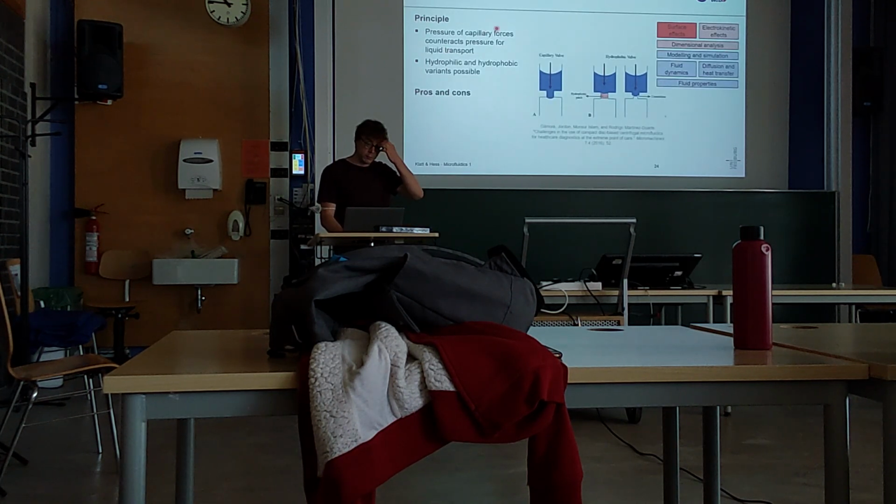So the first one, once again, you can make use of capillary forces to stop liquid movement. It's depicted here. If you have a very small channel and it suddenly gets bigger, you have a pinning effect at this position because of the capillary forces, which prevents the liquid from moving further on.